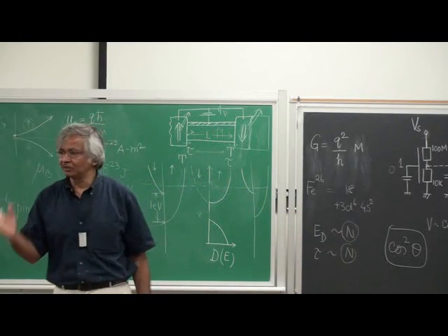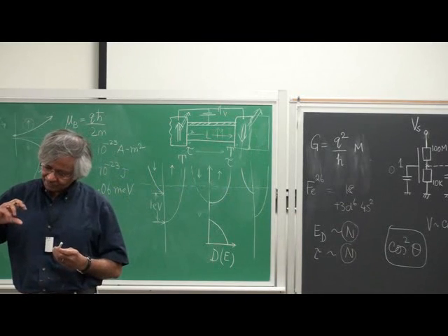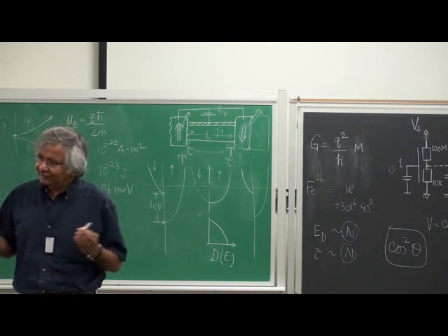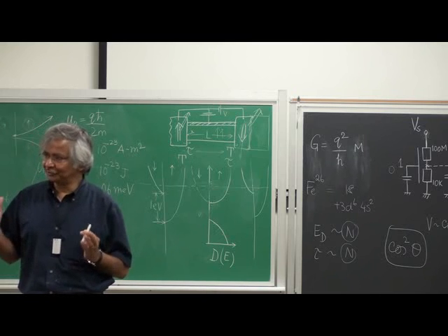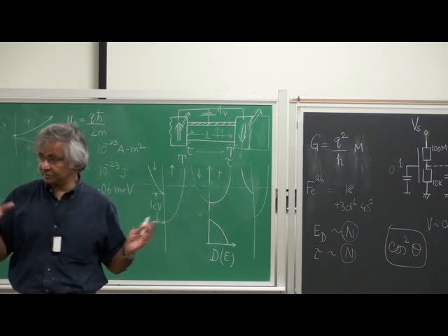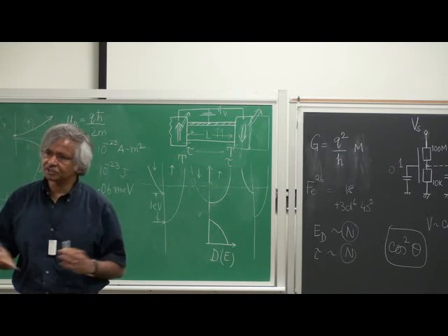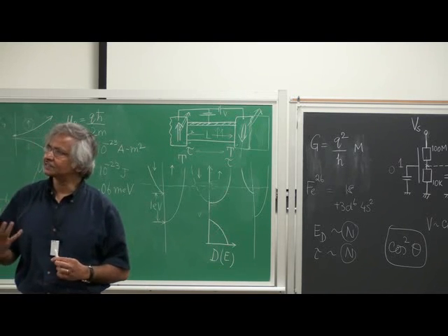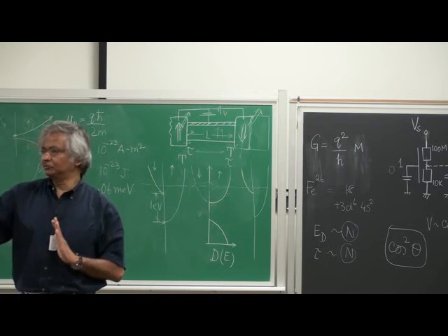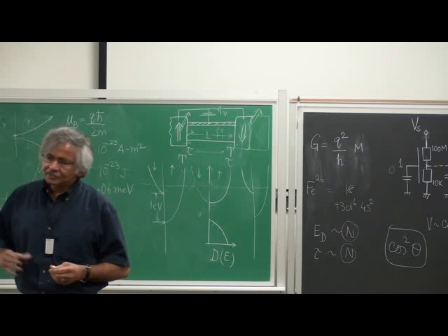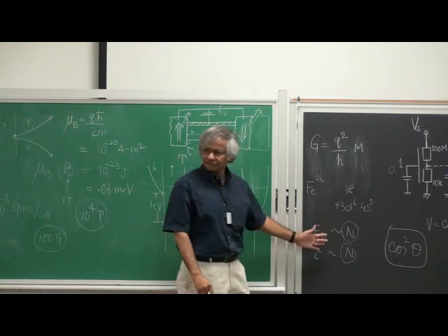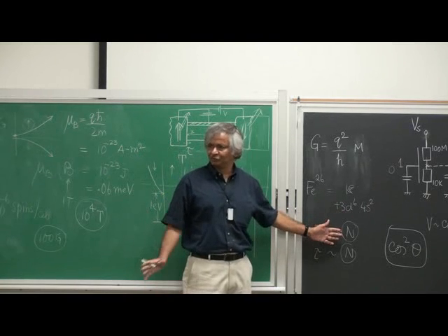Time especially is one that strikes you, because you think of the process of switching a magnet as relatively slow. Maybe even nanosecond sounds too short. But experimentally people have now shown that these million spin magnets can be switched with, I think the fastest I know is like 100 picoseconds. And probably could be made shorter. So with small magnets, it is possible that numbers will look attractive.